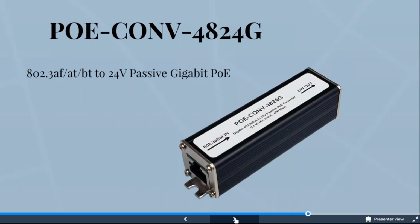Now with that, we do have some customers that come to us and say, that's great, but I still need to power that 24 volt access point. And so we designed this small inline PoE converter. So this will accept 802.3 AF, AT, or BT, or even 48 volt passive, and it'll down convert to that 24 volt.